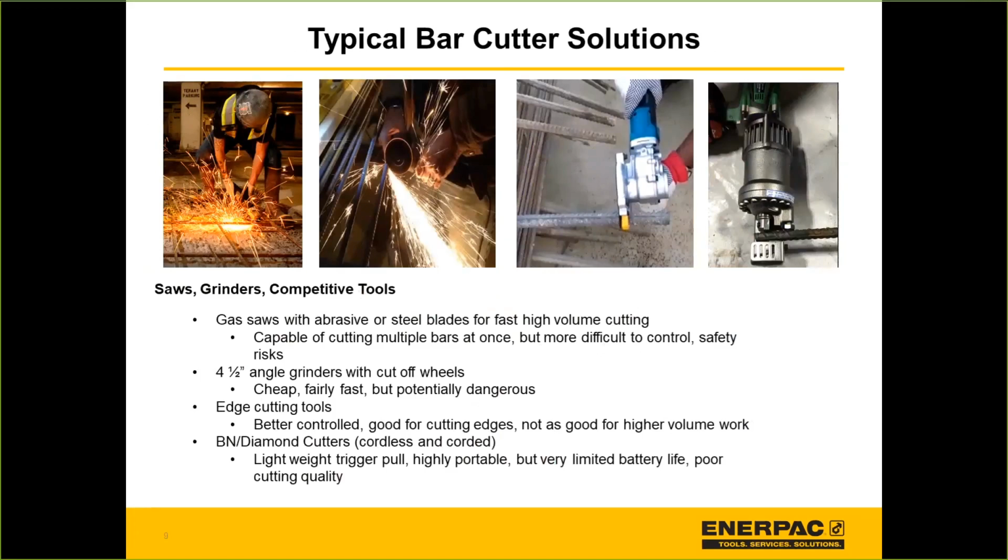But when you're using a solution like this, you just look at the picture and you know you've got sparks everywhere, which means, number one, it can be hazardous to the user or bystanders. And beyond that, if you're going to be using a solution like that on a job site, you're probably going to need a hot work permit. So it's hazardous to use. We know these types of solutions are associated a lot of times with hand injuries, and so not an ideal solution for cutting rebar.